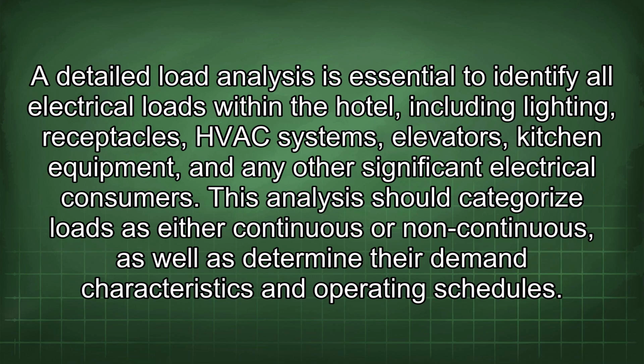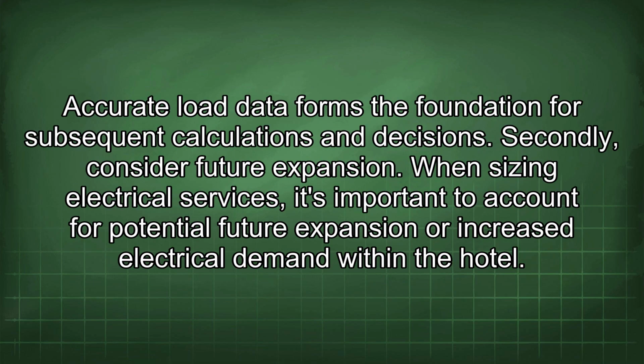A detailed load analysis is essential to identify all electrical loads within the hotel, including lighting, receptacles, HVAC systems, elevators, kitchen equipment, and any other significant electrical consumers. This analysis should categorize loads as either continuous or non-continuous, as well as determine their demand characteristics and operating schedules. Accurate load data forms the foundation for subsequent calculations and decisions.